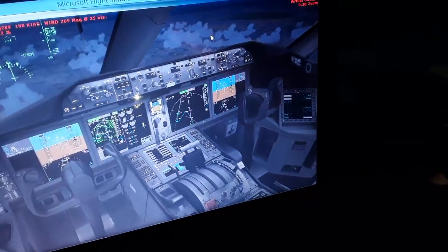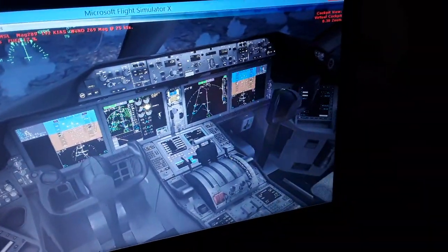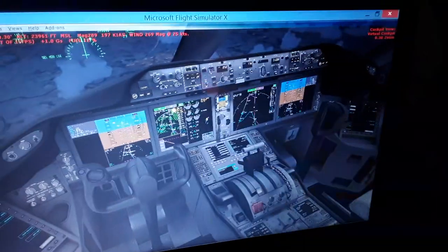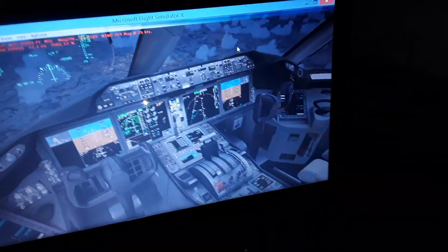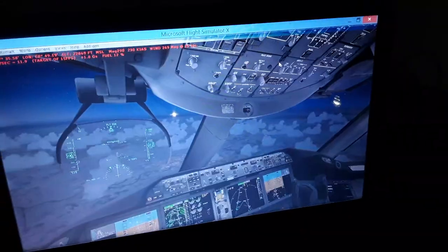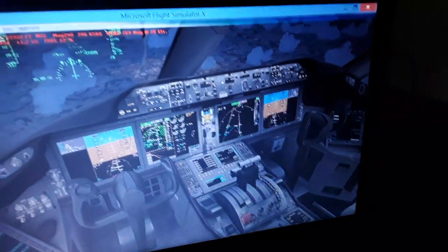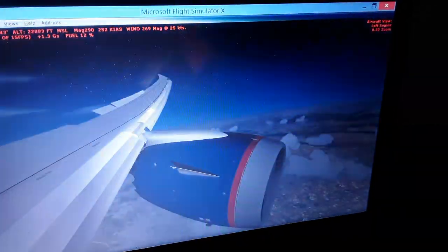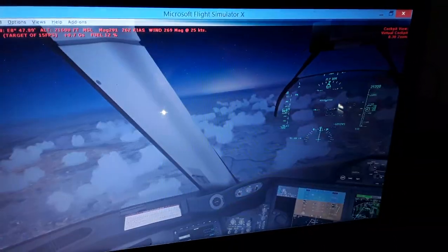So we start descent now, back to the airport, flaps retracted over here, and also speed brakes extended to increase the rate of descent. Spoilers. So we put the yoke down and follow this flight plan we have created. We have 6 more minutes. We use a little bit more thrust over here as we descend. So it's better to have a little bit more time.